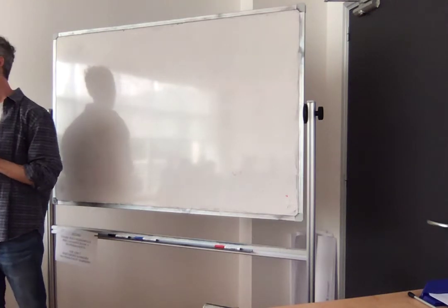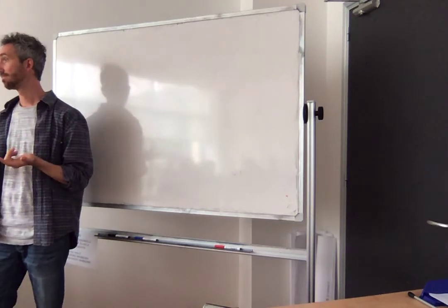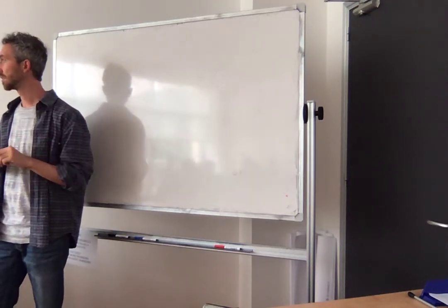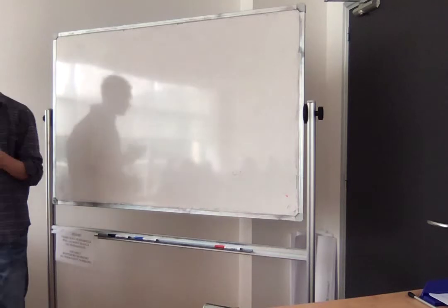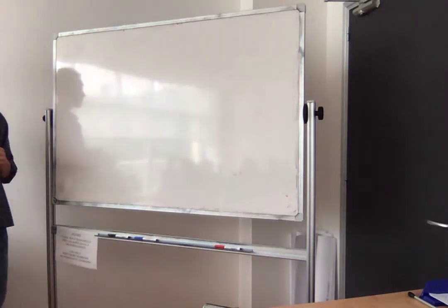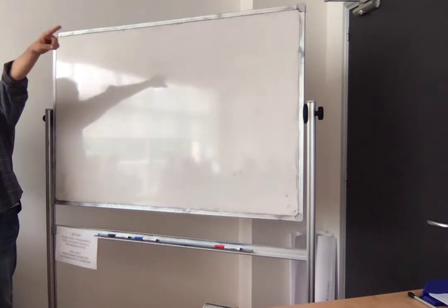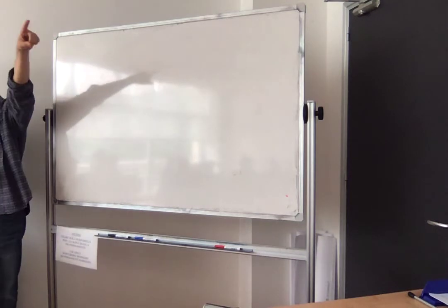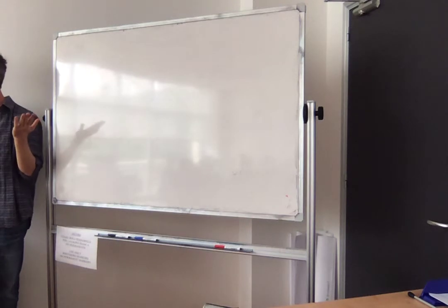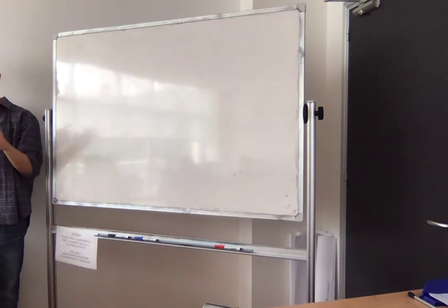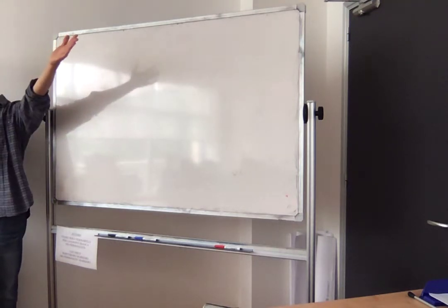So that's nonlinear. And nonlinear, of course, means that your optimal control problem is going to be non-convex, which is never a nice thing. So ideally, we would like to make this linear. And the good news is that under some reasonable assumptions, we can do it. And I will try to show you how. So actually, the first equation is already linear, right? M C double dot plus G equals the sum of F. That's linear. I have no multiplication between state and control. Actually, the state doesn't even appear in that equation.